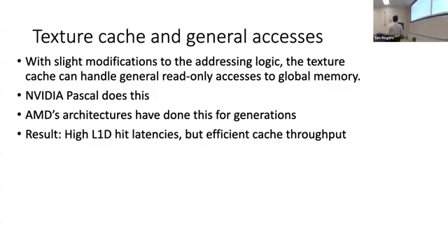In the early days of GPUs, and even still today in some lower end or graphics-centric cards, they didn't want to bolt a shared memory together with the L1D. In fact, there was no shared memory. Well, was there in the very earliest CUDAs? I don't remember if there was, but it wasn't very big. They didn't want to mess with that scratch pad. The scratch pad is on its own. And then if you're going to global memory, good luck to you. We'll maybe throw you in the texture cache because if there's some spatial locality, you should be better.